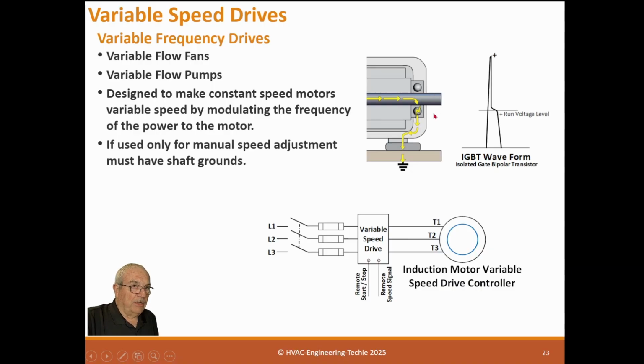And normally we put a little ring right here that has a metal brush that brushes the shaft and grounds it to the ground of the motor, and that way it protects the bearing. But that's what does it, the IGBTs. Now, you can never trust some VFD drive salesman telling you, oh, our drive can't do that. It's nonsense. Every drive does it.